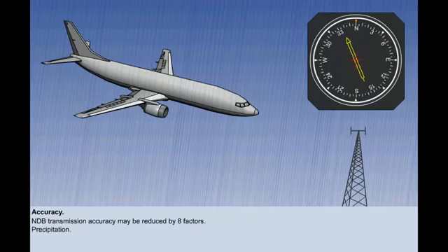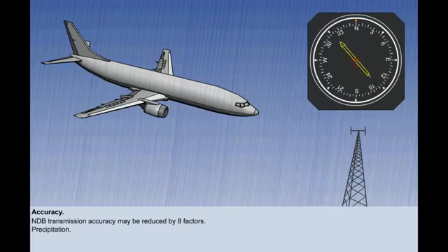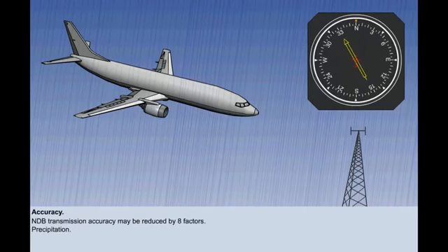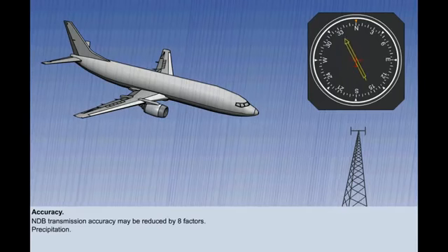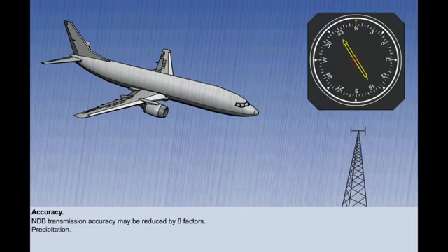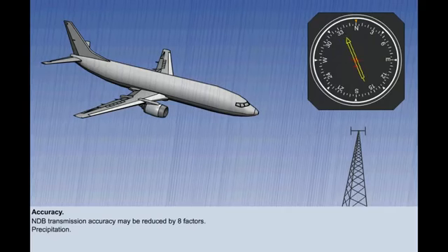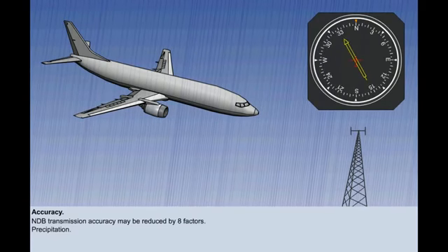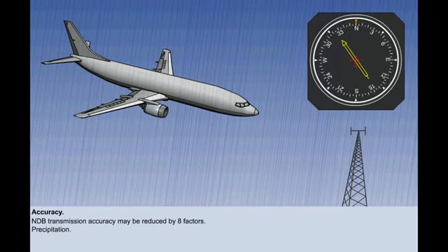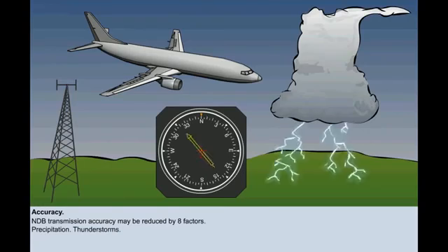When water droplets or ice crystals collide with the aircraft, there is a reduction in the signal-noise ratio and a consequent wandering of the RBI or RMI needle. The audio signal will have a background hiss, which is also likely to be present on VHF frequencies. Thunderstorms produce large electrical discharges across the electromagnetic spectrum, including long wave and medium wave. The effect on the ADF is to make the needle point to the offending cumulonimbus cloud or clouds, so that the instrument is completely unreliable.